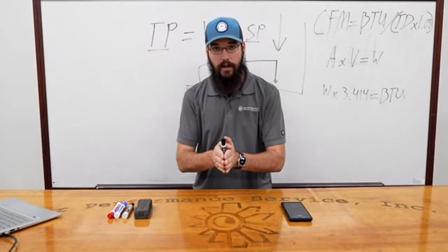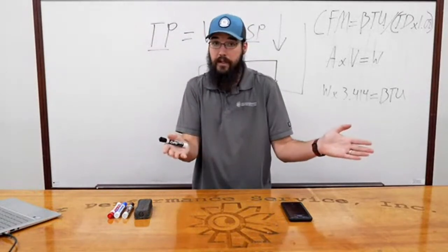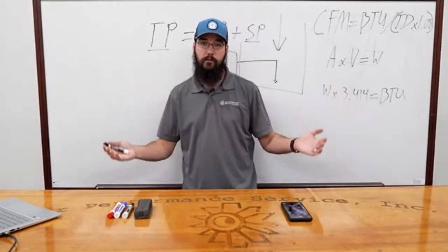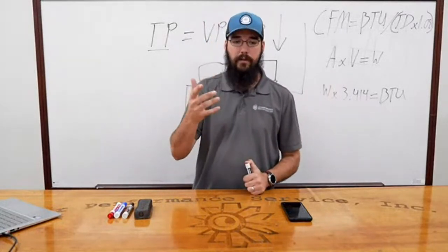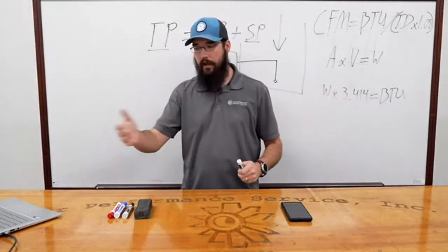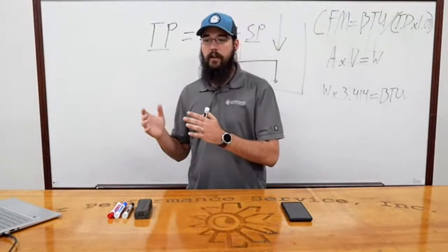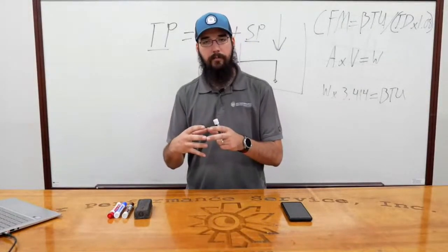Anyway, we get a call for really high humidity. It feels sticky. It's uncomfortable. We're at set point, we're satisfying set point, and heck, we've got it turned down to 70 degrees. It's still uncomfortable. What the heck's going on here? Well, that's a high humidity call, typically. So very likely you're moving way too much air. You need to slow that air down, and that's somebody that just rammed that adjustable pulley the wrong direction.